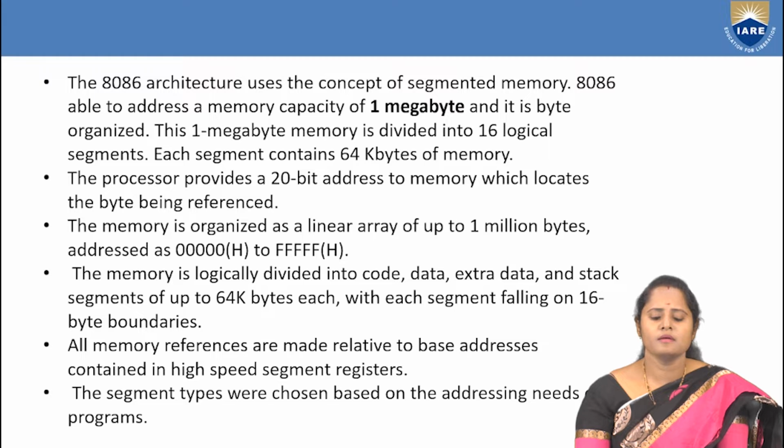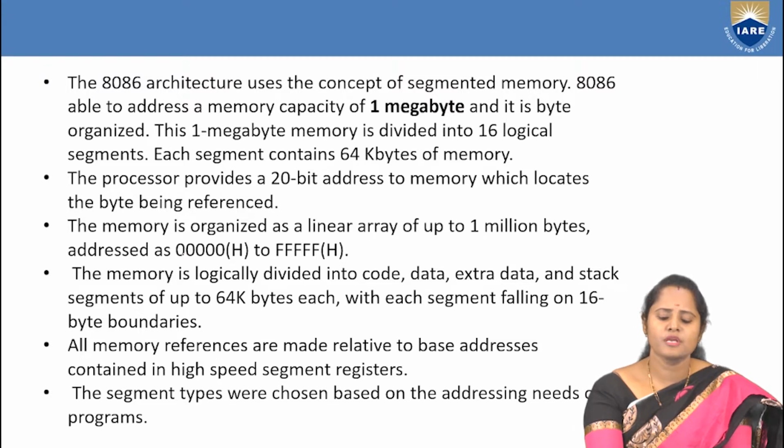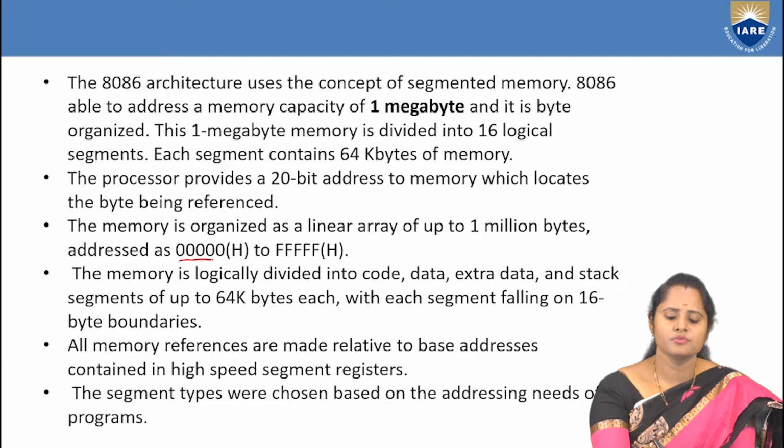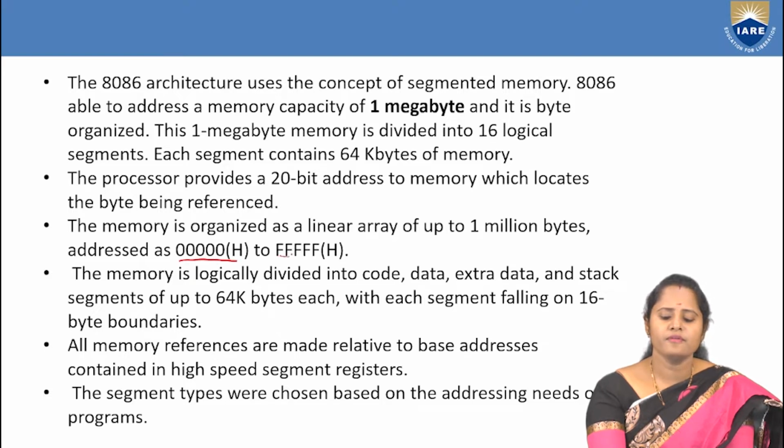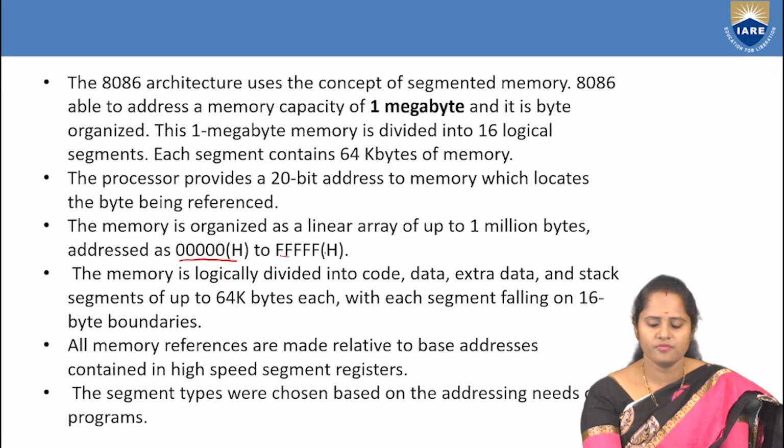This 20-bit address will start from the memory location 00000H to FFFFFH. The memory is divided into 16 logical segments, and as we said, each will serve a different usage. That is, the microprocessor memory is divided into different segments.